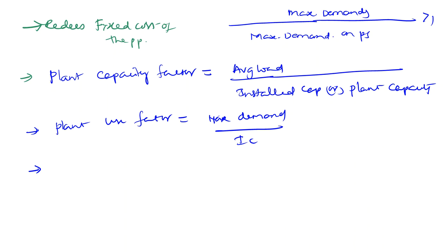There is one more formula which may occur from an examination point of view. It is reserve capacity, which is important also. Reserve capacity is the difference between the installed capacity and the plant capacity. In examinations, they won't give installed capacity and plant capacity directly, so you need to use the above formulas for the calculations. Next we will discuss power system protection.